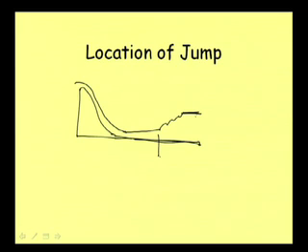Say we have this y2 dash tailwater depth, and first we need to see if the upstream flow is supercritical. If it is supercritical, then only a hydraulic jump will form, and at the downstream of course we will have subcritical flow. Now, if the corresponding depth is y1, then we can calculate the sequent depth y2.